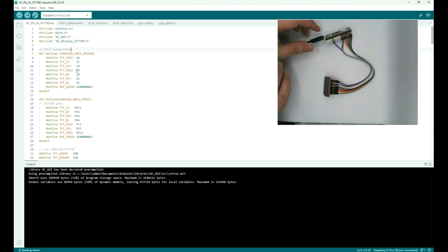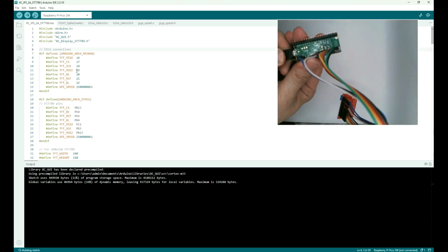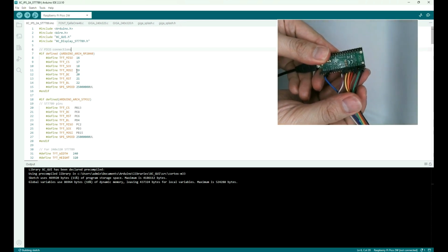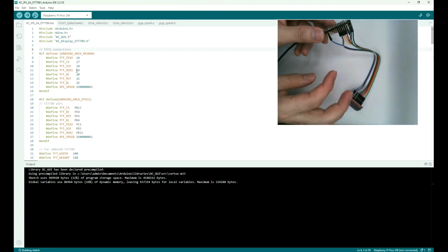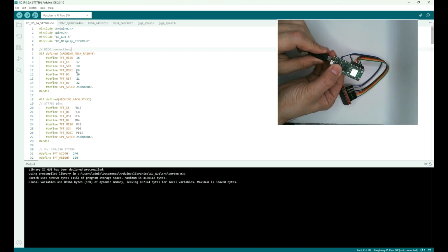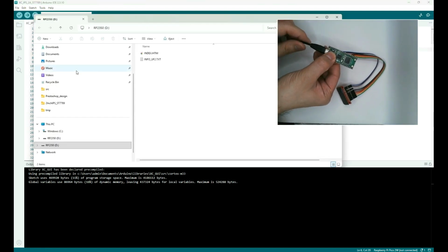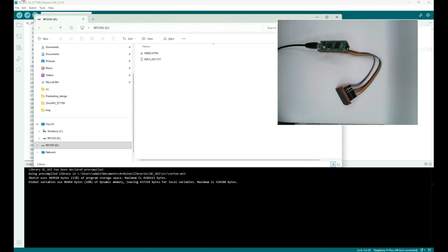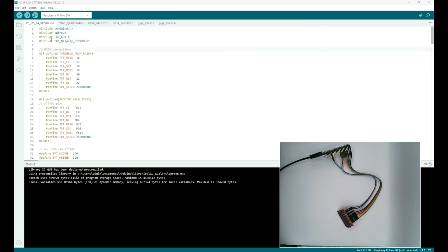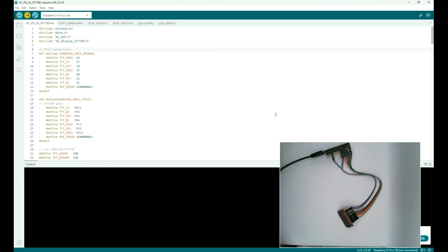Now I will put the Pico 2W into flashing mode. To do that, I will hold the BOOTSEL button and then plug in the USB cable. We should see the UF2 drive appear shortly. Now, let's upload the program to the board and check the result.